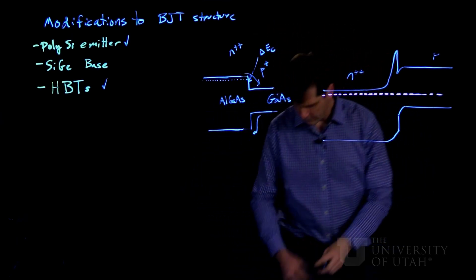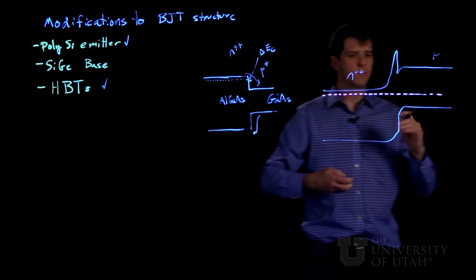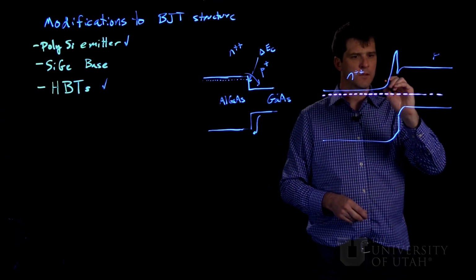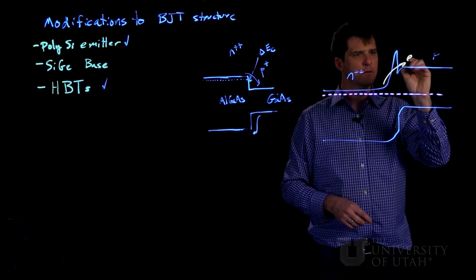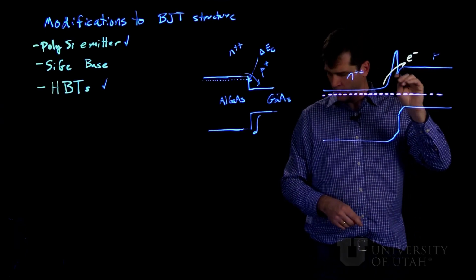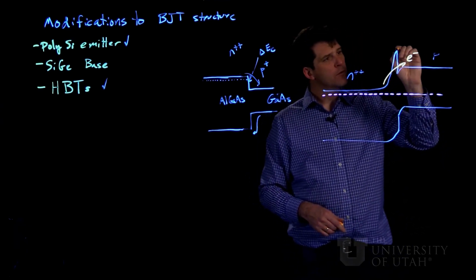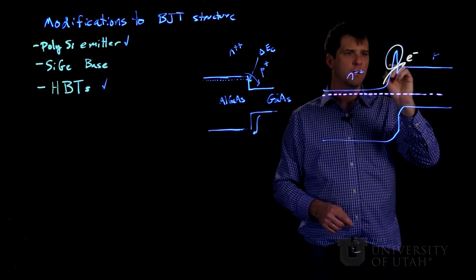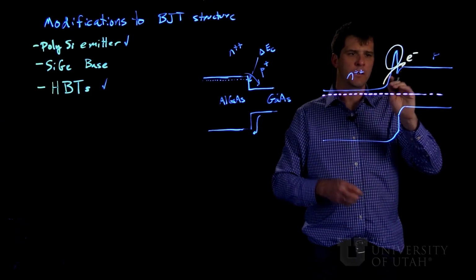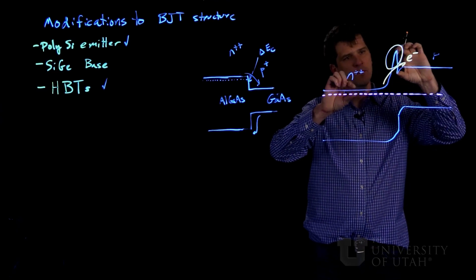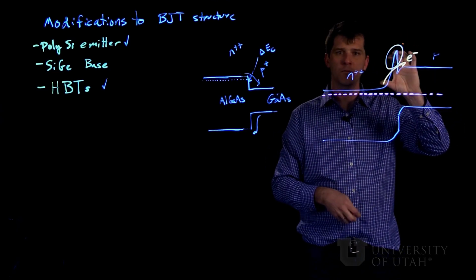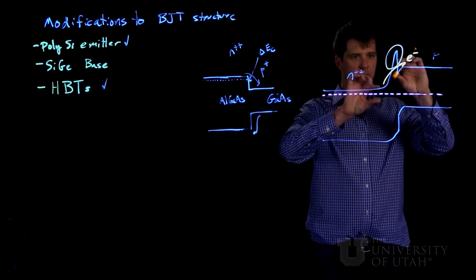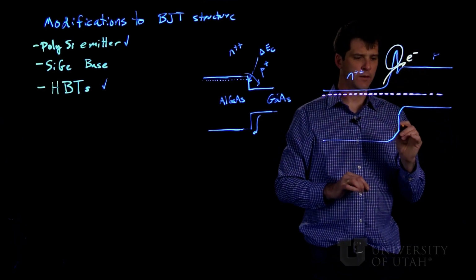Okay, so when we look at the emitter going into forward bias, what we're doing here is injecting electrons through this small spike, but of course tunneling can help there, and the details of this band offset compared to the built-in voltage on this side will help determine where these energy levels line up.